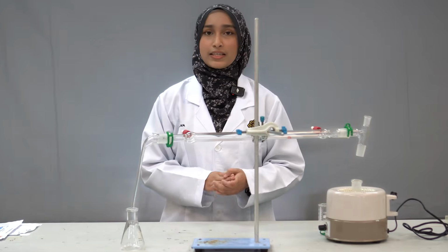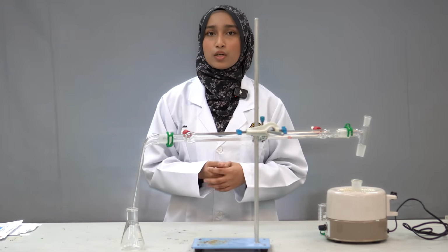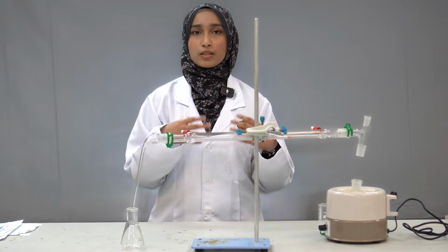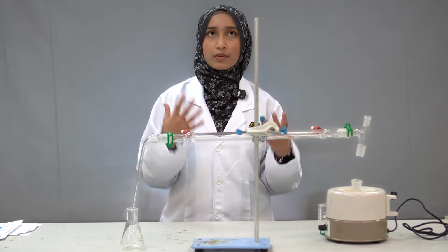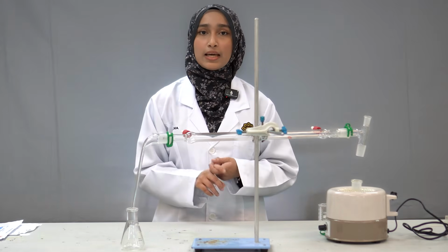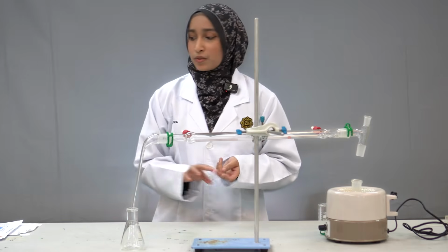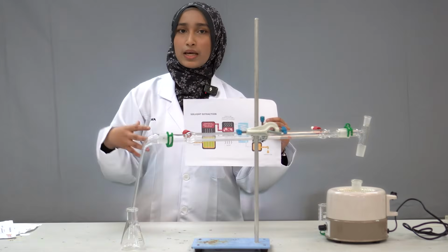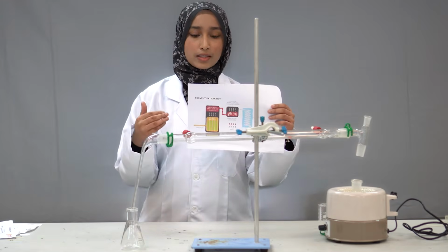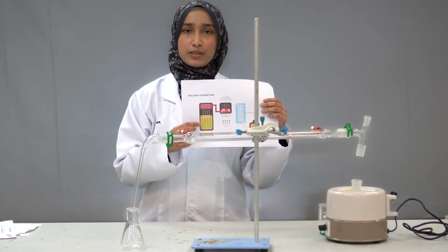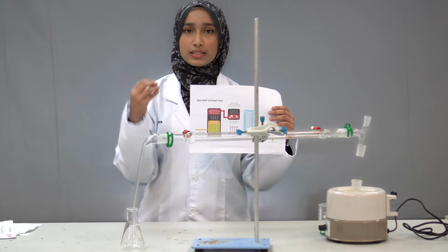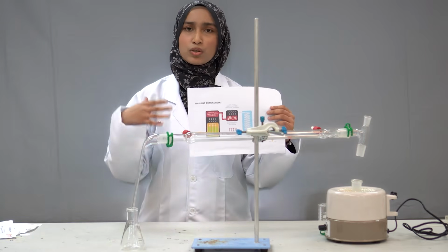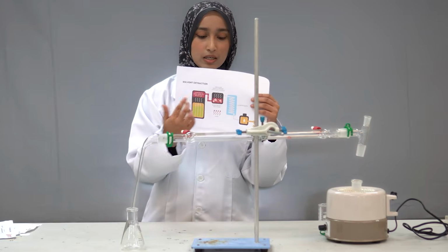And then the second application is essential oil extraction, which implements the steam distillation process as a common method for isolating essential oil and flavor compounds from plant material by heating and condensation. So this process uses hot steam. When the hot steam passes through the plant material, the heat energy from the steam will break the oil glands and vaporize the essential oil in the plant. So this oil becomes vapor. It will mix with the steam.